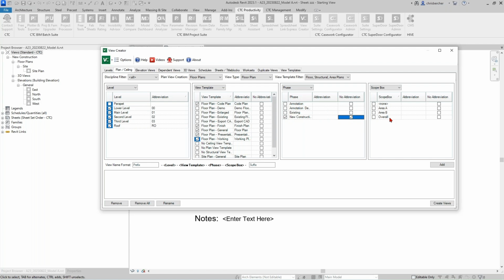And none of these are going to be dependent based, but they are all going to be attached to the overall scope box. And depending on what ones you're going to use to do certain things later on, you can incorporate some different options here for how you want to manipulate this. The last step is, how do I want this labeled? And the order in which these tiles are visible here is how it's going to be named. If I don't like the order right now, I can change it.